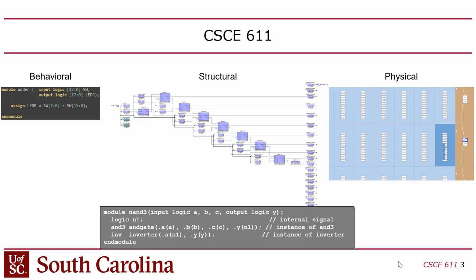And then the place and route is when you take each of those gates, each of which can actually be placed on an actual physical resource on the FPGA. You put them on there and then you connect them together. So it's the same process actually that hopefully you guys did in 2.11 with the breadboards. It's exactly the same thing.